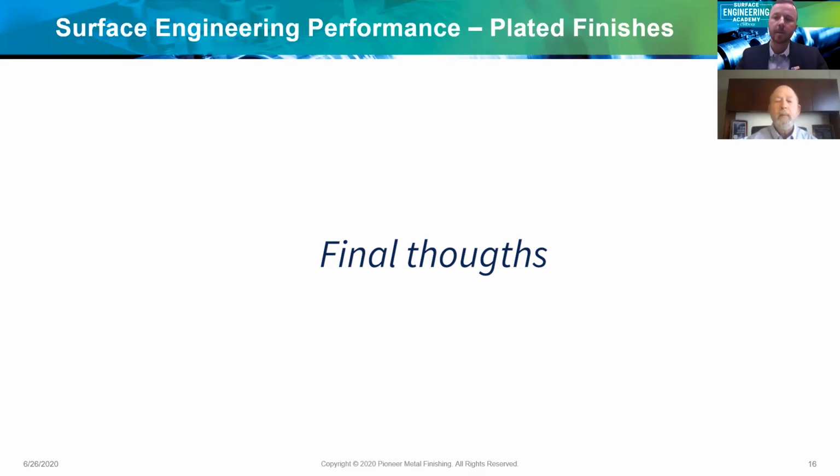Yeah, that's a good point, Steve, especially around material hardness or even incoming material and the latency of some of the incoming materials. I think of stainless and some of the challenges those would present, and then of course the availability of a strike to promote proper adhesion and all of the different intricate pre-process steps that can be required for success there. So yeah, to your point, having a strong mutual two-way open relationship with your metal finisher can really help avoid a lot of those pitfalls. It's the best way to create a robust process at the lowest cost.